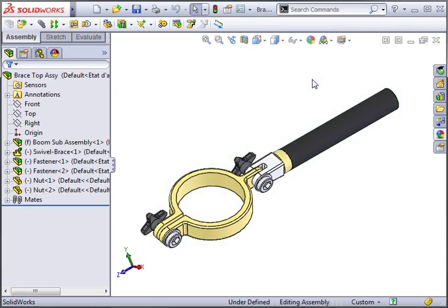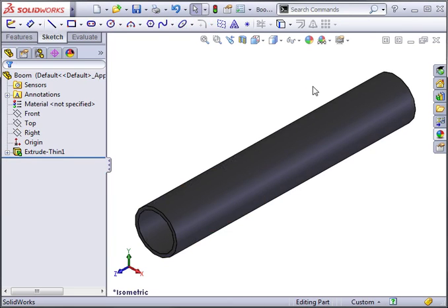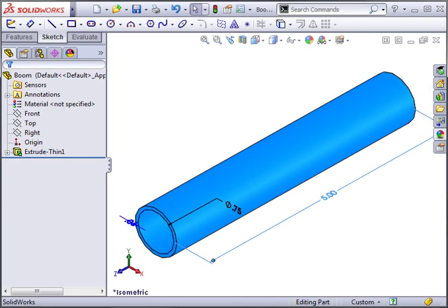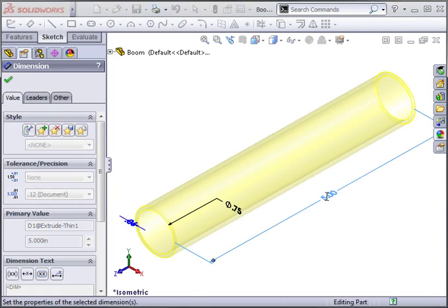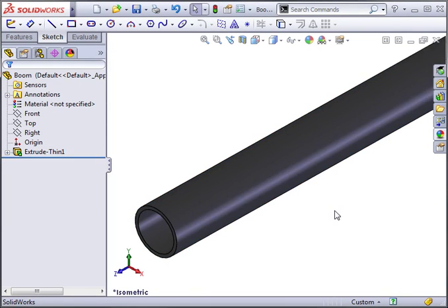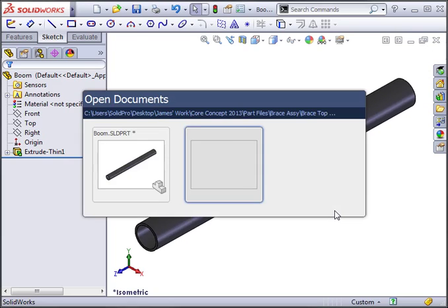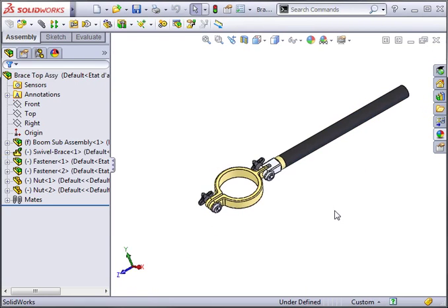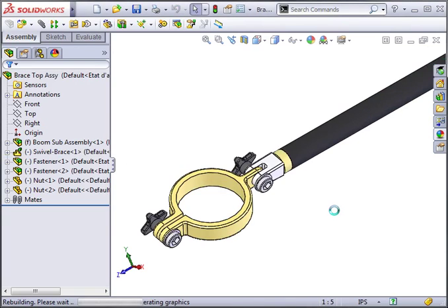You can see how modeling in a parametric environment can be very powerful. The other huge advantage of this type of system is that you also get associativity between your parts, assemblies, and drawings, meaning if you make a change to the design of a part, the change will take effect in any assemblies that it's a part of. And its 2D drawing will update automatically as well.